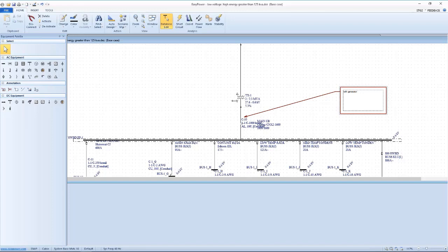So in our arc flash ratings, we may label for the generator rating because the generator is higher, or worst case, or I can rate it with the utility and then insert my label contents for the generator. In either case, my label will be different than what the one line tells me.